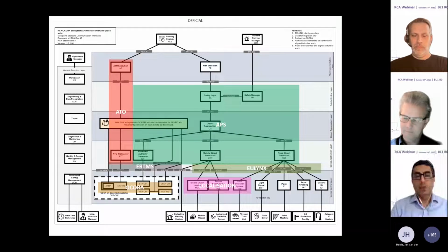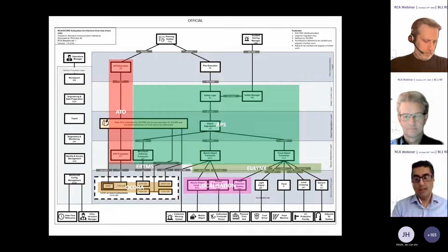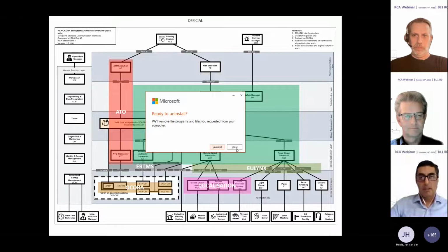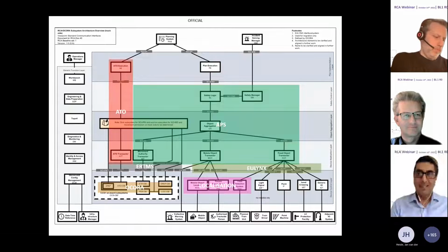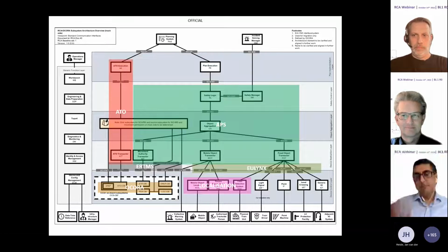And finally, one example of where we've adopted certain aspects of ETCS in the latest standard is around localization. One of the key architectural drivers is being able to harness the explosion of data with intelligent trains, and trains being able to provide a lot more information about their length and position at a higher granularity, but also being able to use different types and different sources of localization, and then being able to aggregate that into one piece of information that can then be used by the safety logic.